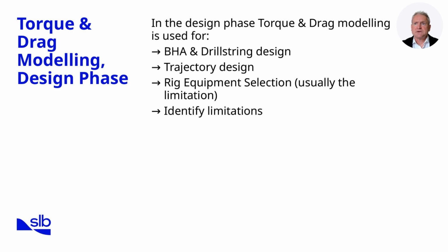By modeling drag and torque across various inclination and azimuth builds, we can identify sections that might cause excessive side forces or high friction factors. This allows adjustments to the well path before execution, reducing the risk of stuck pipe or premature tool failure.